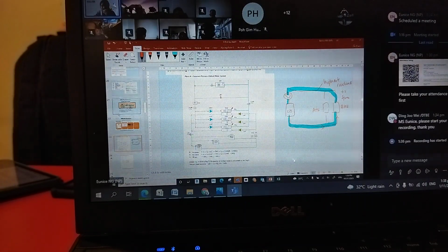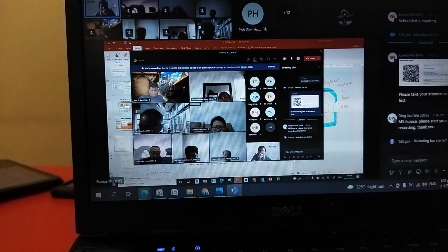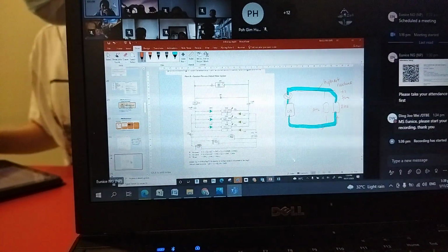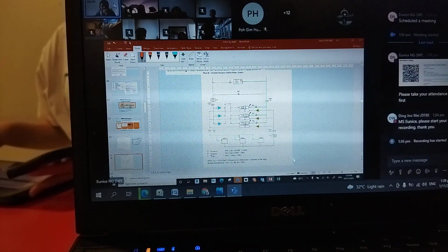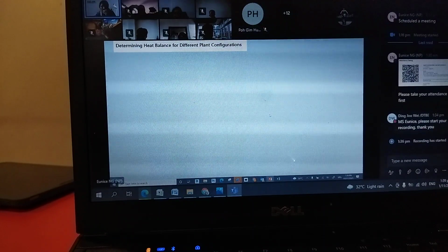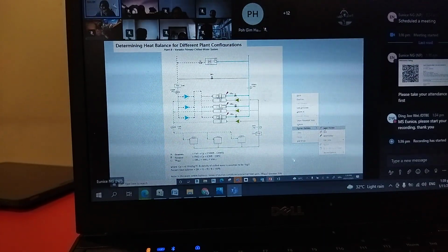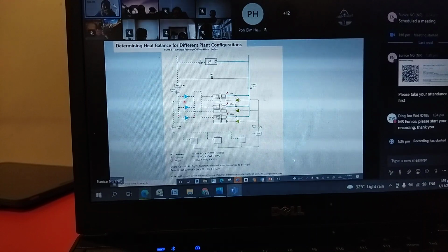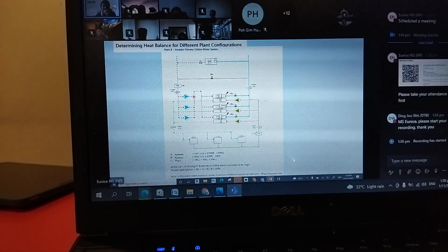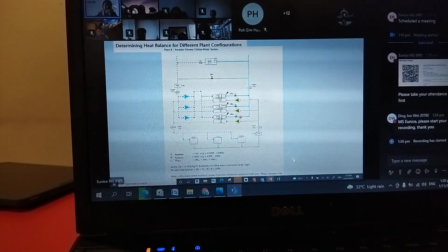Any question on the first arrangement? Any question? No, good. Okay, do the second one. The second one is like the first one, except that they are now supplying chill water to a common header. This is a common header. The pumps are supplying water to a common header, and all this water will be gathered together and pumped to whatever pump that is running.